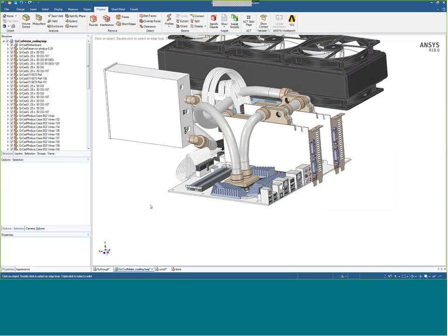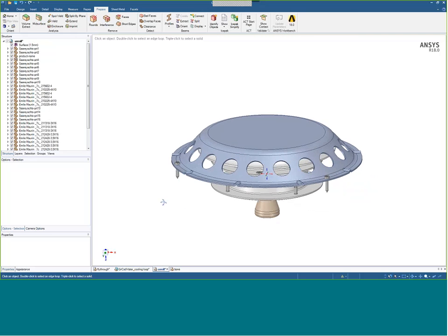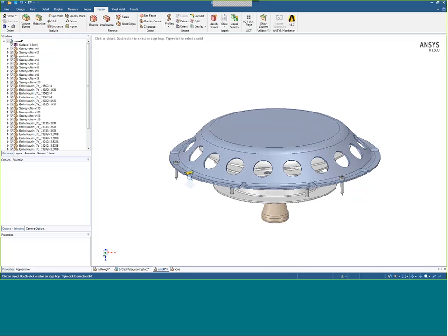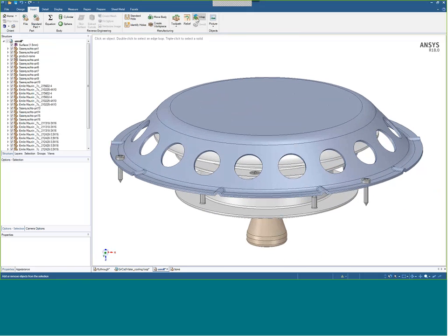To go to some of the other features that we talked about as well, one of the things I wanted to point out was the ability to use unroll. I actually had a few questions that came in about wrapping and can we wrap 2D or 3D. In the past, under this Insert tab, we added the ability to wrap. This will wrap 2D objects onto geometry, and it will also wrap 3D objects that are basically 2D extrusions.